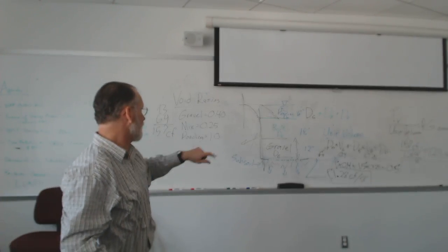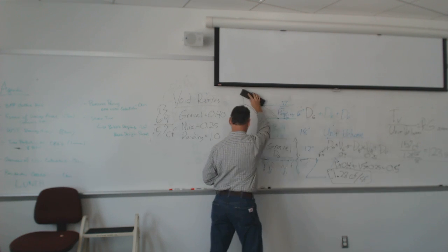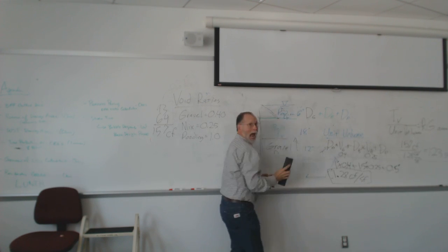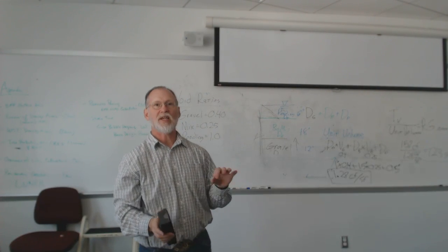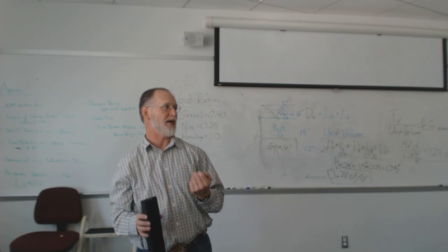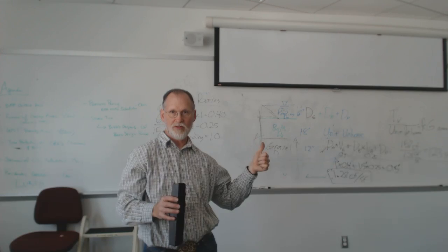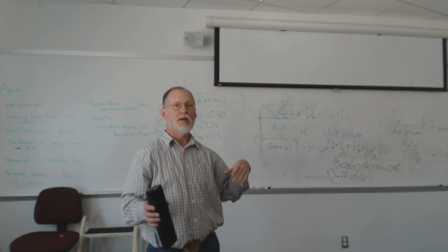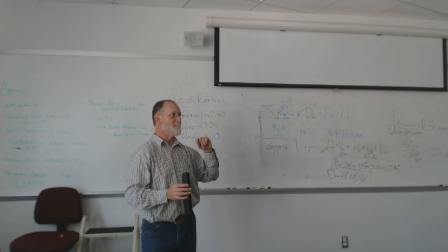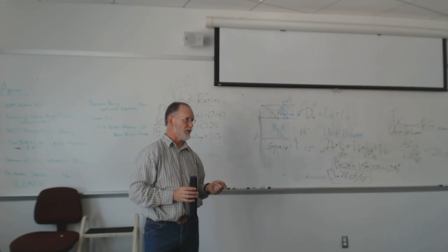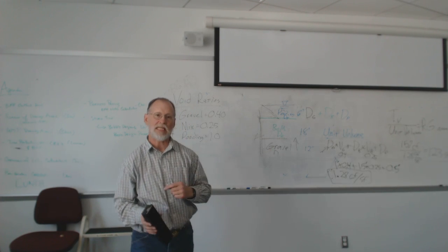These are pretty typical numbers, but you can definitely use different numbers, and that's what we're going to do next. Is that related to your soil, the suggested ratio? No, there's not a suggested ratio. If you want to write something down as far as typical ranges, your rain gardens are going to be at least 6 inches, this is for larger rain gardens, 6 inches to 12 inches of ponding depth. The minimum biomix that I've seen in any regs, I think Virginia's micro bioretention in DC, is 18 inches.